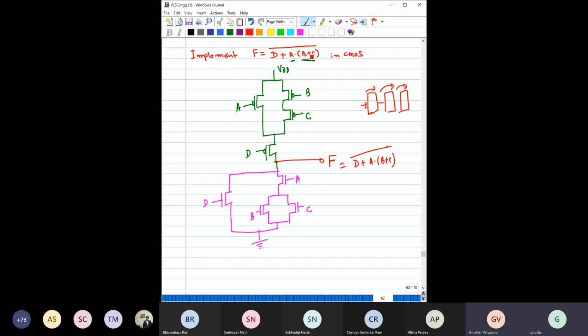Oh, another complement. Okay, good question. So in that case, probably you have to go for multi-stages, or you need to split it and represent it like this, so that there is only one bar like this on top. We can do the B plus C whole bar as B bar dot C bar, and we will directly feed B bar and C bar instead of B and C. Yeah, that means we can basically get that.